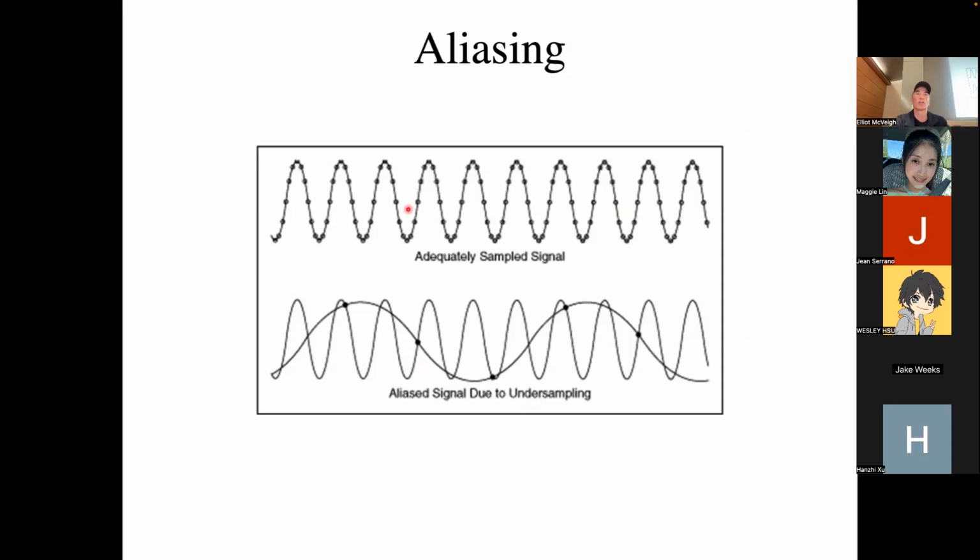And another way to describe aliasing is this, where I have a sine wave and I'm going to put a sampling comb to see what's there, right? And so I've got a lot of points for each full cycle of this sine wave. I don't know how many, like 10 points or something along each cycle. So that would seem to adequately sample that sine wave, right? I know where the peaks are. I know the frequency. I could give you the phase shift, like how the whole thing is shifted in time with that kind of sampling, right?